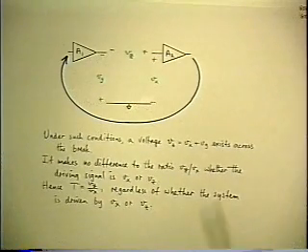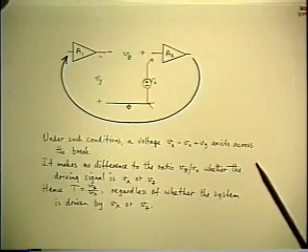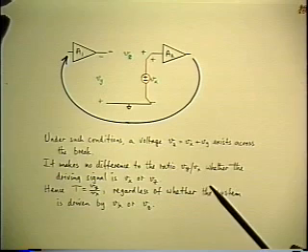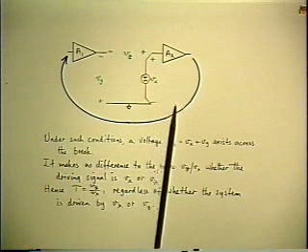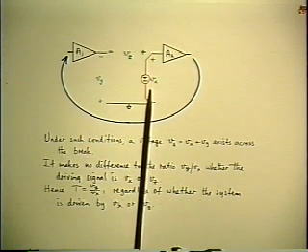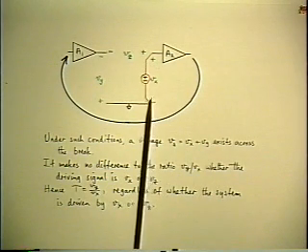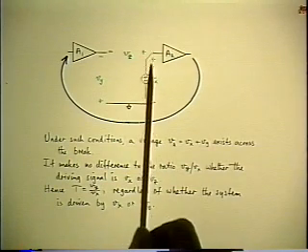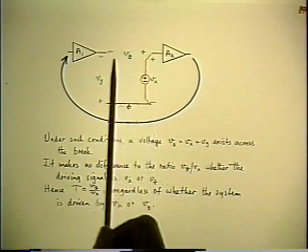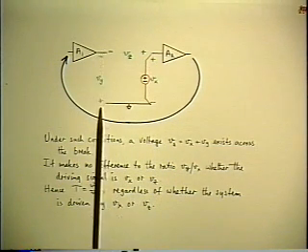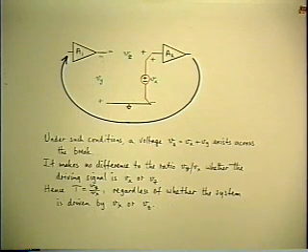Here's the same thing again. There's our independent source, assuming that in practice we have re-established the operating point. Okay, here's my signal generator, and just to make things concrete, let's assume that it's 1 millivolt AC, at 1 kilohertz or whatever. I can take a voltmeter and hang it across the same point and measure that 1 millivolt. I take the voltmeter and move it over and measure Vy, and suppose it reads 10 millivolts. Then the loop gain is 10 at that frequency.